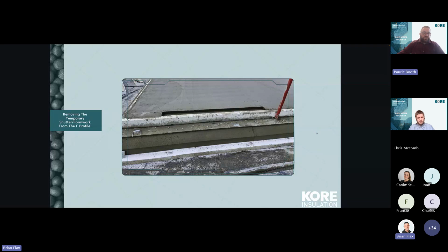Here are more pictures to show that the temporary shutter has been removed. You can also see at the top of the slab that a recess has been left in the slab as an access way for doorways. With the profile removed, you've applied the cut along that cut line to ensure that there's no undermining of the foundation system. Everything's sitting there and it's all ready to go ahead with wrapping up the radon barrier and installing the blockwork.